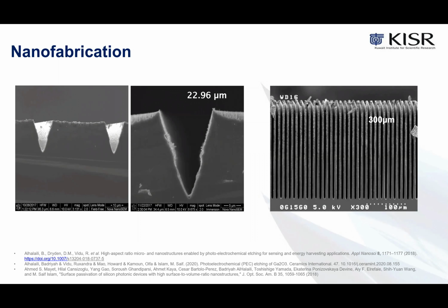Nanofabrication is highly important to build electronic devices by the top-down approach. So the investigation of etching techniques is very important for the preparation and fabrication of devices with controlled micro and nanostructures, especially in the third and fourth groups of the periodic table, due to their importance for optoelectronic devices and nanosensors. Creating deep holes on the surface of the substrates is still a challenge and requires more control to increase the surface area of the substrate to obtain new, different properties.